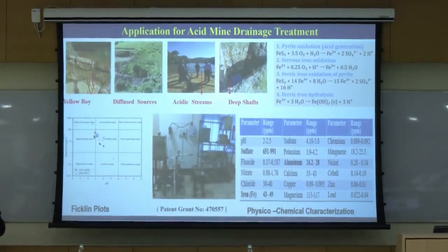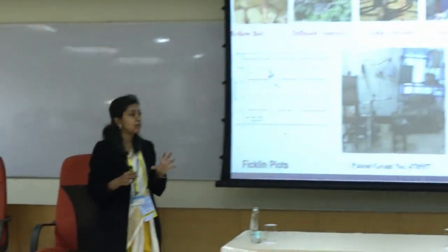So this is like an incremental research. So we started with understanding of the problem, and especially in the northeastern state of Meghalaya, we did a lot of field work, and so, like I said, a lot of geochemical interventions. And so these streams that you see, these pristinely blue streams, these are very highly acidic. Their pH is around 2 to 2.5, which makes them unsuitable for any kind of human or animal consumption. So this is exactly 3 hours from Shillong, the outskirts of Meghalaya, and despite the abundance of water resources, tankers had to be deployed, which is ironic.